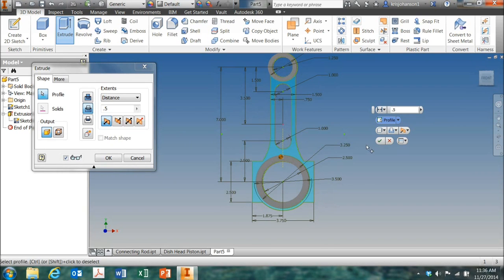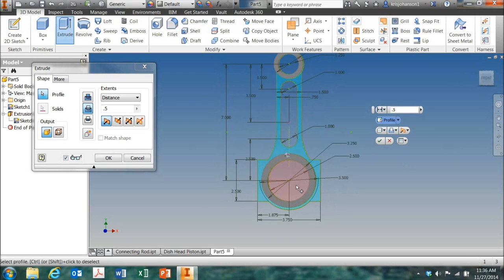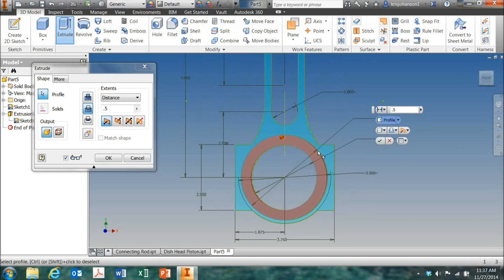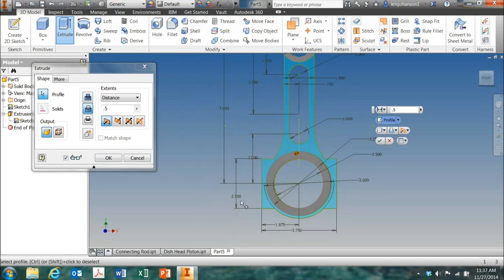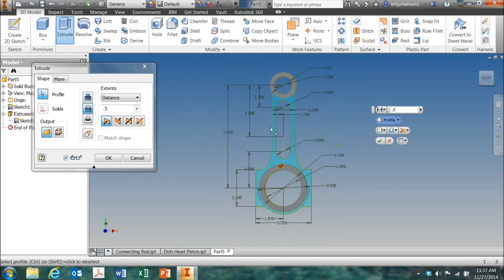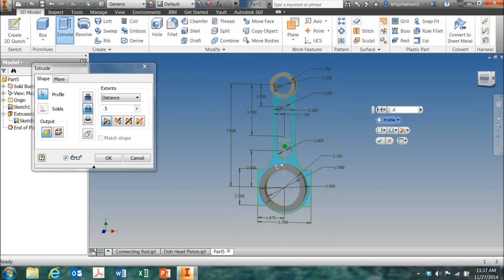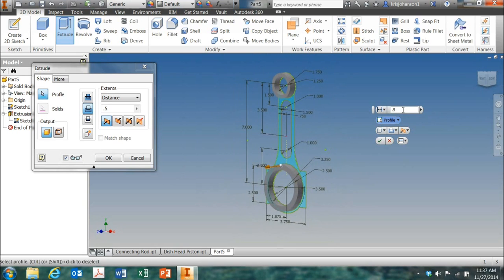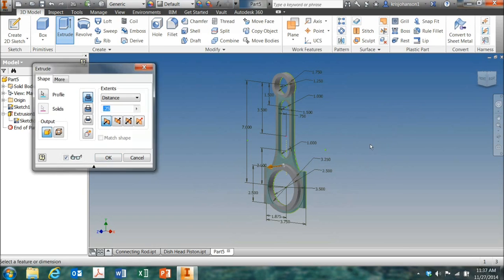If you can't, then go back to the sketch, I guess, and make sure you've deleted all the correct little line segments here. This has to be a closed surface in your sketch in order to select it. This one I want to extrude only 0.25 inches and make sure I'm going the right direction. So it needs to come out of the page as well, 0.25 inches.